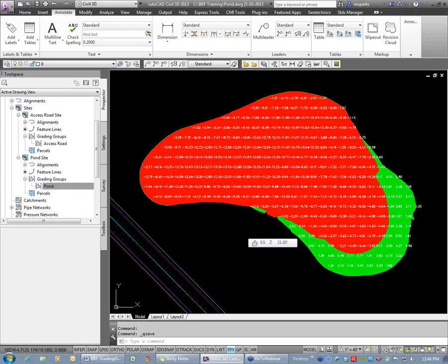That's probably the preferred method if it worked all the time. But like I was saying, it typically happens in a larger site, I usually have problems where the automatic surface creation happens. So if it does start crashing and becomes unusable, which I'd say maybe a quarter of the time, which is more than it should be, but it does happen, then I would have to uncheck that and add the feature lines manually to the surface like we did with the access road.